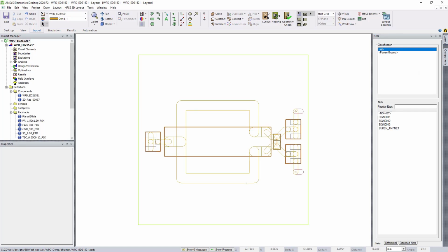Inside the Ansys simulation and design tools, we may wish to modify some of the elements in the design. Within this, we're going to make some modifications and pass those back into DesignForce. Now, remembering that some elements are controlled and managed, the layout engineer has full authority. For example, for manufacturability, we would choose which layer stack to be used and also the vias and the pad stacks. So when I come on to the vias, we'll look at that in a bit more detail.